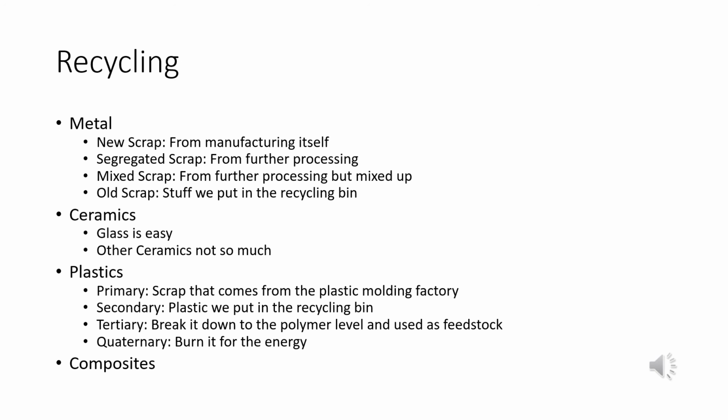Ceramics, glass is pretty easy, right? You just chop it up and remelt it. You've got to get the paper and things off. In fact, I just saw where there's a great big sand shortage in the world to make cement. And they're actually grinding glass up and using that as mortar sand. And it's really kind of a neat process. Ceramics, that's kind of tough, right? All this is cooked clay. How do you recycle that? There isn't really a very good way yet.